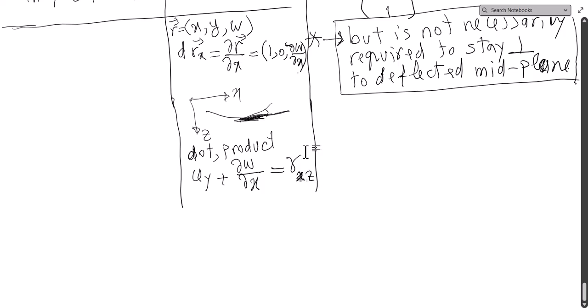And then if gamma is 0, then we will recover the relationship that we had for the Kirchhoff plate theory, which is phi y is minus dw dx, if they want to be perpendicular, or shall we say the cosine of 90 becomes 0, right? So if cosine 90 is 0, then this relationship will recover the Kirchhoff theory.